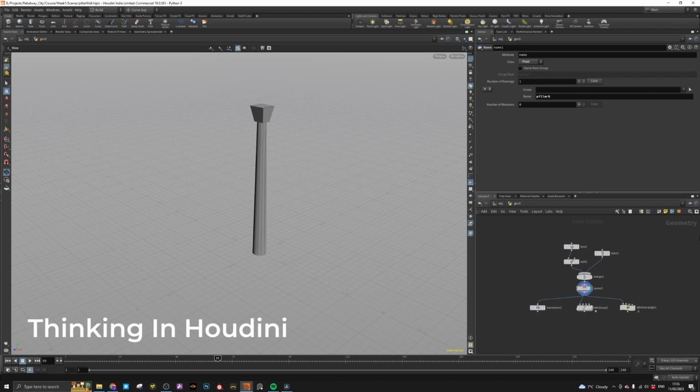As we already spoke about before, whilst modelling procedurally in Houdini, we require a shift in thinking. Rather than directly modelling and moving components around, it's often better to think about it as indirectly manipulating the geometry. And how we do that is by accessing the information that makes up the components.